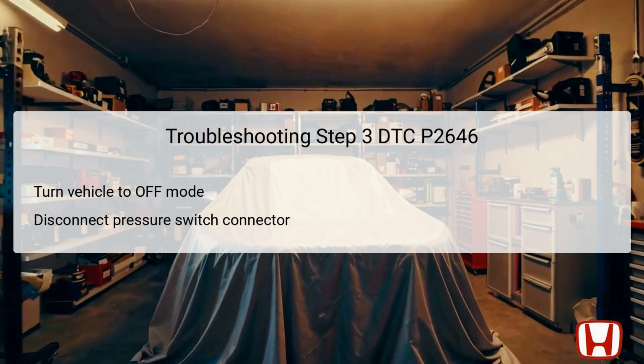for further analysis. Conversely, if the indication is negative, troubleshooting advances to step 4 to assess the VTEC system's oil pressure. The fourth step in troubleshooting DTC P2646 entails checking the oil pressure at the rocker arm oil pressure switch A. This involves removing the switch and attaching specialized tools, including the pressure gauge adapter, to measure real-time oil pressure. Once the engine is started, monitoring the oil pressure during the VTEC plus VCM test is crucial, with the benchmark being that it should reach approximately 392 kPa, equivalent to around 56.9 psi.